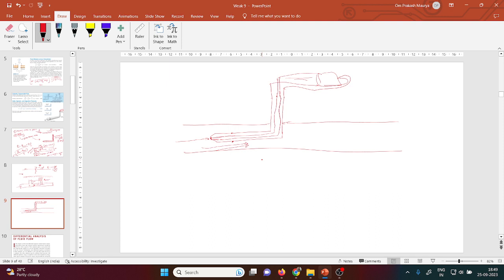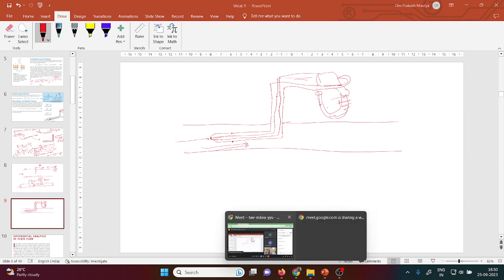Here you can also use a manometer. These two pipes are connected with the manometer: one pipe is for the pitot tube, and the other is the perforated pipe, and the mercury is there. When the pressure is applied, the mercury rises, and the difference in height we can easily measure like that. The whole concept behind the pitot tube is that. I think, Francis, your doubt is clear on that.